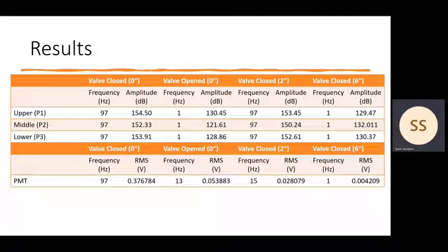This proves that at the lower ends of the pipe, the combustor is pulsating, thus making a sound which we observed in the lab. We can also see that the frequency is 1 at 0 inches when the valve is opened. Buoyancy is produced by the combustion, which causes an upward draft in the tube for acoustic oscillations to occur. However, when there is an escape route for the heat other than the top and bottom of the tube, these acoustics will not happen.